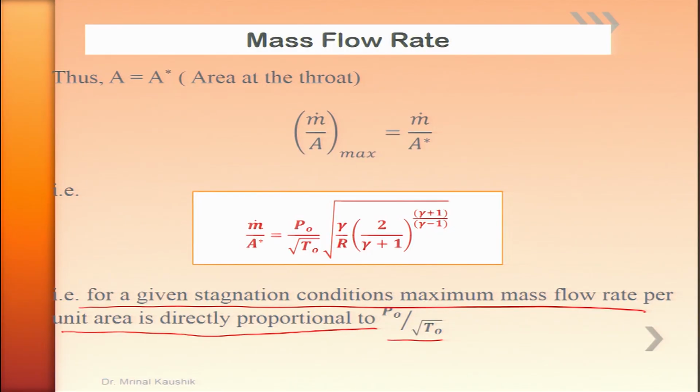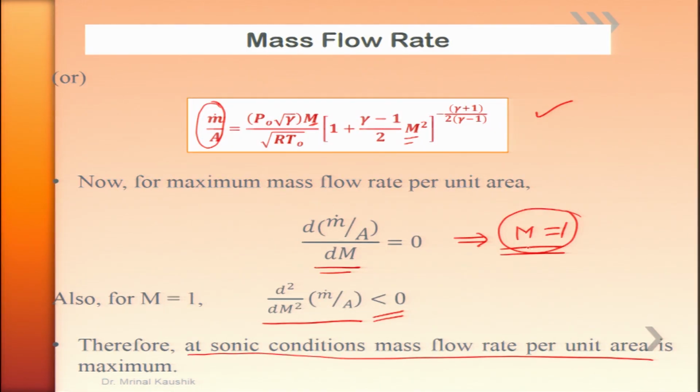Now, moving on further, if we replace A under this condition, what we have just obtained, that under m equal to 1, the area here becomes the throat area, and throat area that too becomes under m equal to 1 choking condition. The throat area is generally in a convergent divergent nozzle represented as AT.